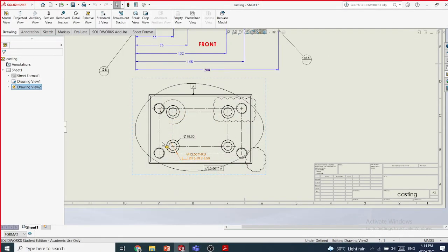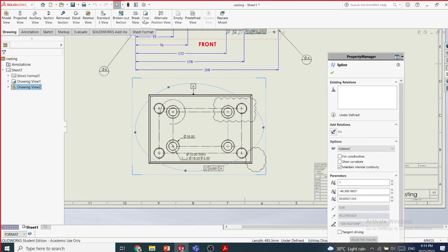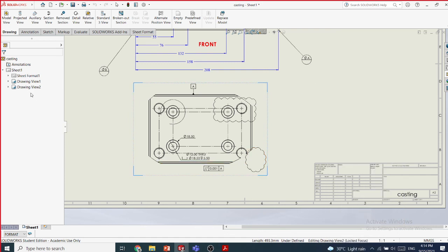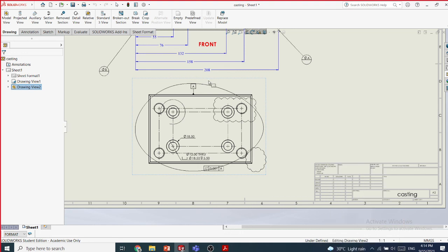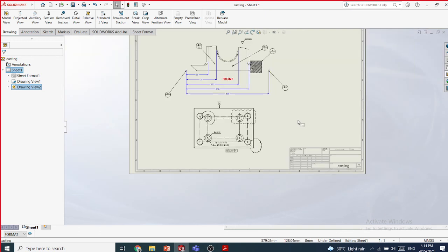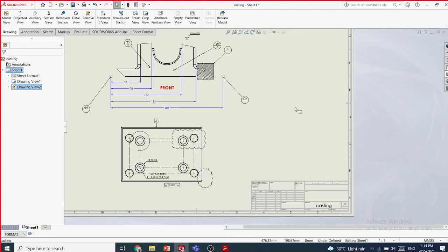Okay, so just remember that. When I have a crop view and I crop it again, you will get these areas cut, and you can go to the correct view here and edit the crop or remove the crop. Then you can delete this unnecessary group and get the original view back. Okay, so please make a note on that, how to reverse the operations.